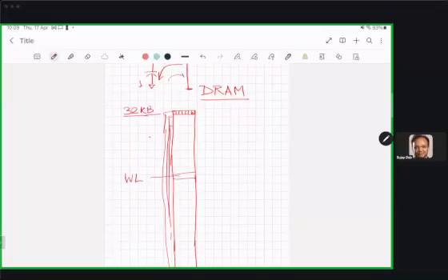Now the biggest enemy of achieving performance in a compact circuitry is these long wires, because we are making transistors faster and faster by shrinking them, etc. But the wires are not shrinking. And as you have a long wire, the wire behaves like a transmission line. So it has capacitance, inductance, and resistance. And because of which the delay provided by this wire will be significantly high.